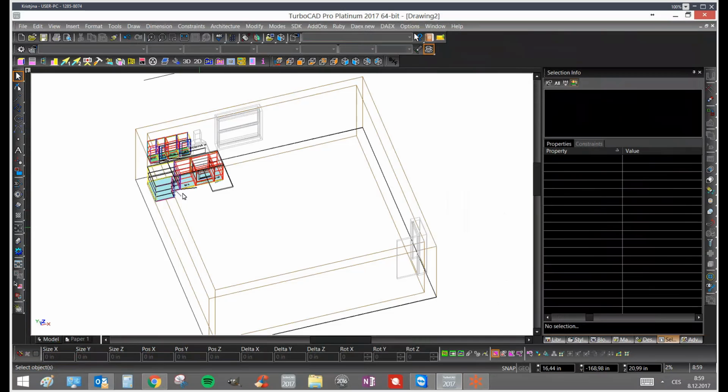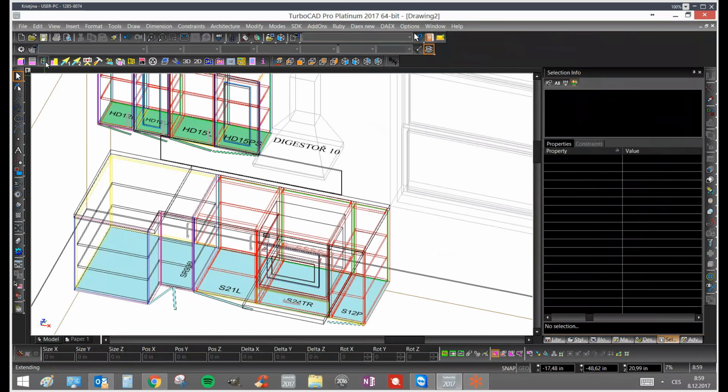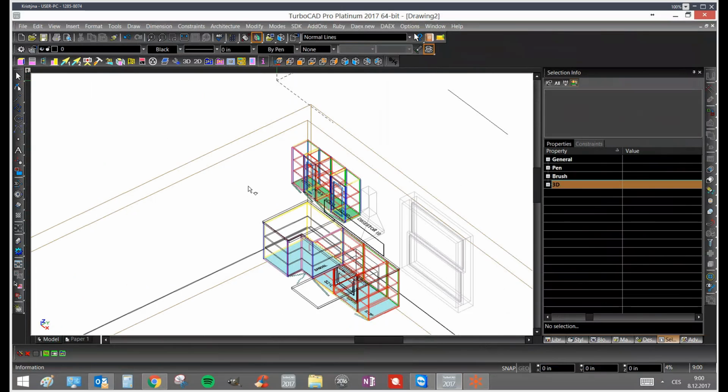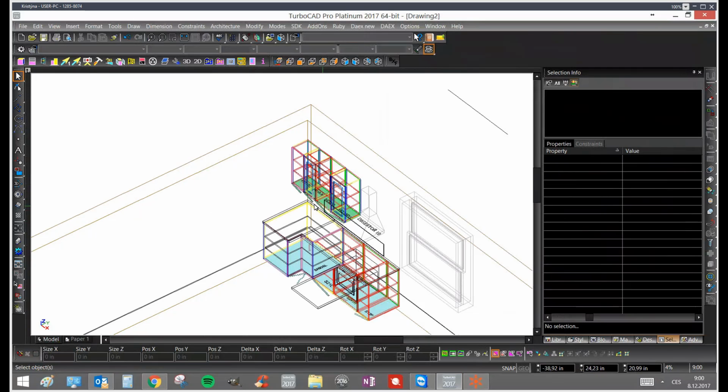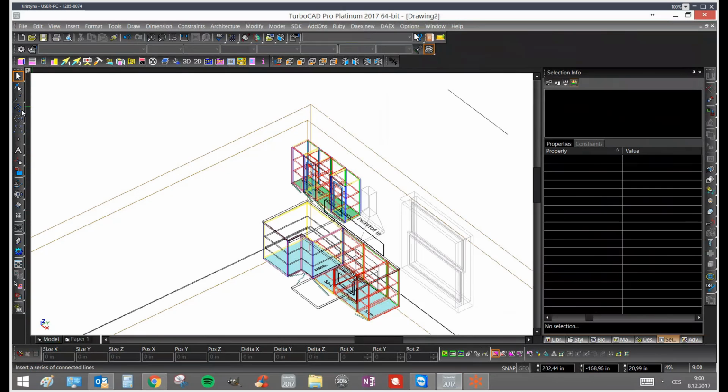So would you like to see any other length materials like tiling and everything? Okay, I can show it to you if you want. If you want to put tiling, you have to put the work plane on the wall, and then again you use the polyline, but it has to be closed.